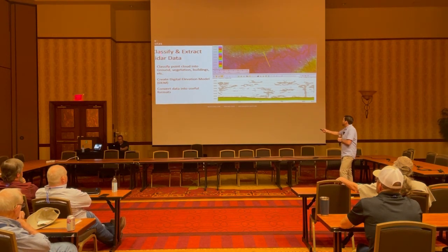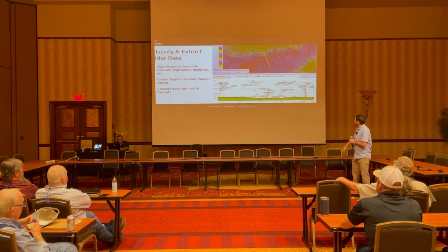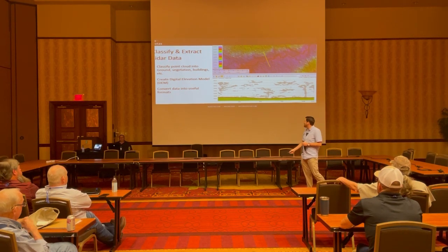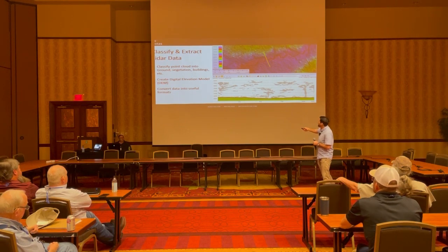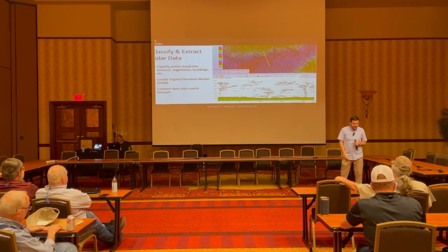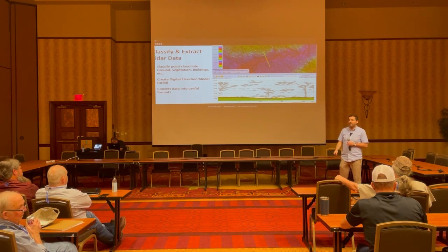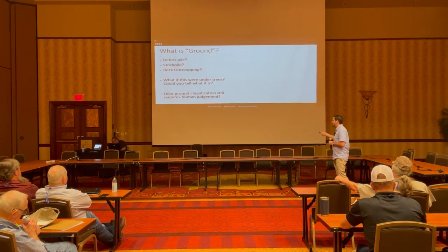Extracting that, like I said, you classify everything, and typically our methodology is to take the LiDAR data or the point cloud data and then convert it into a digital elevation model. And that means we're taking what is a point cloud or a vector data set and turning it into raster data, which I think is on here. I'll talk about that in a second.